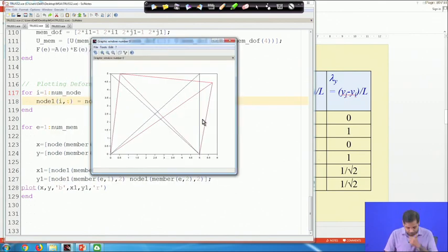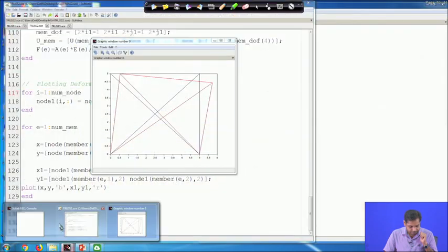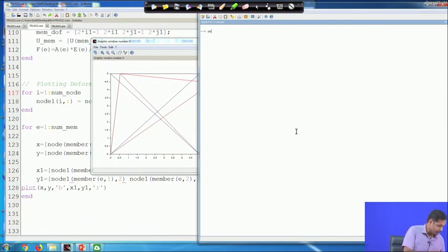Okay. Now, again similarly, if you take the determinant of Kg, the determinant of Kg will be 0, which is a very small number, effectively 0. Similarly, if you take the determinant of the member stiffness matrix, say any Ke, this last one, this will also be 0.